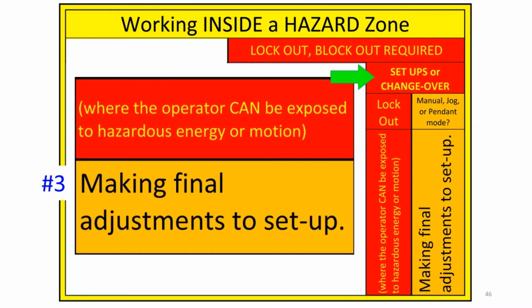One of the frequent questions that comes up has to do with changing belts on a stroke sander. You can't change the belt properly without air pressure in the cylinders, right? Well, you may leave the air pressure on, but you must disconnect or unplug and lock out the electrical power for belt changes.